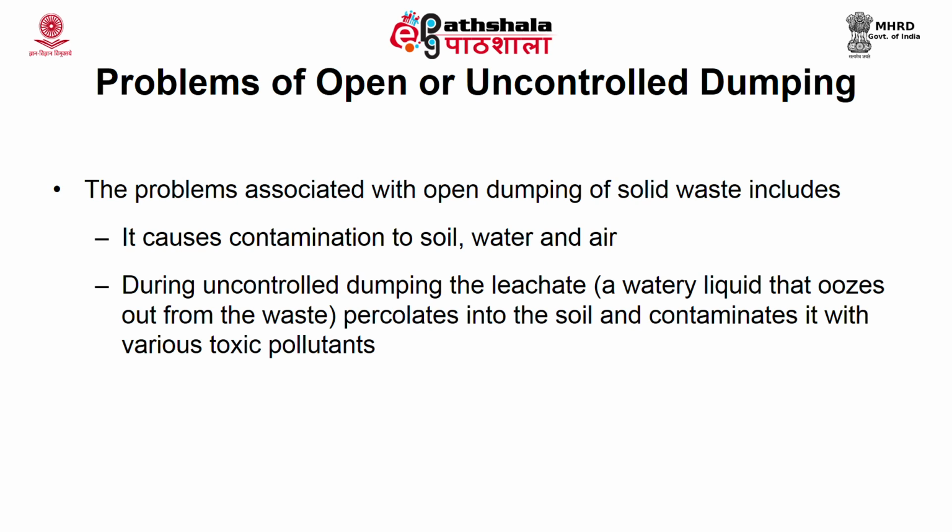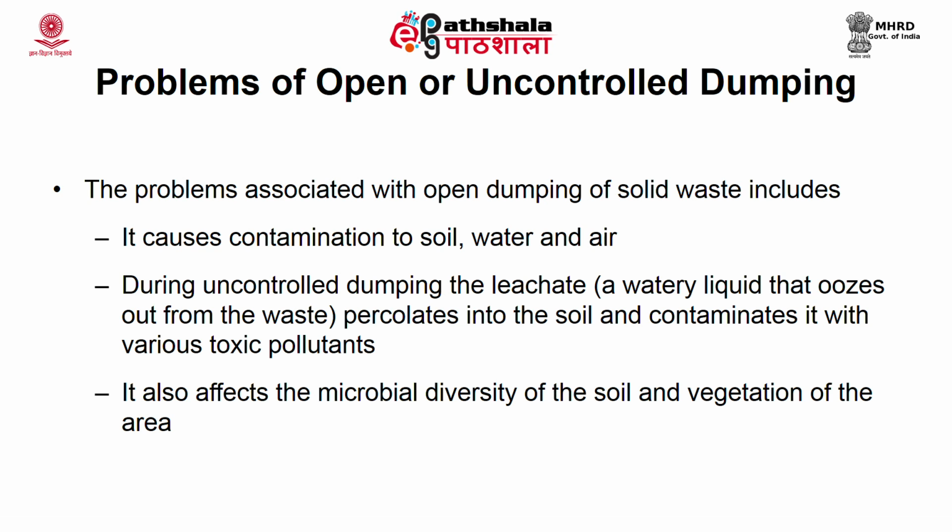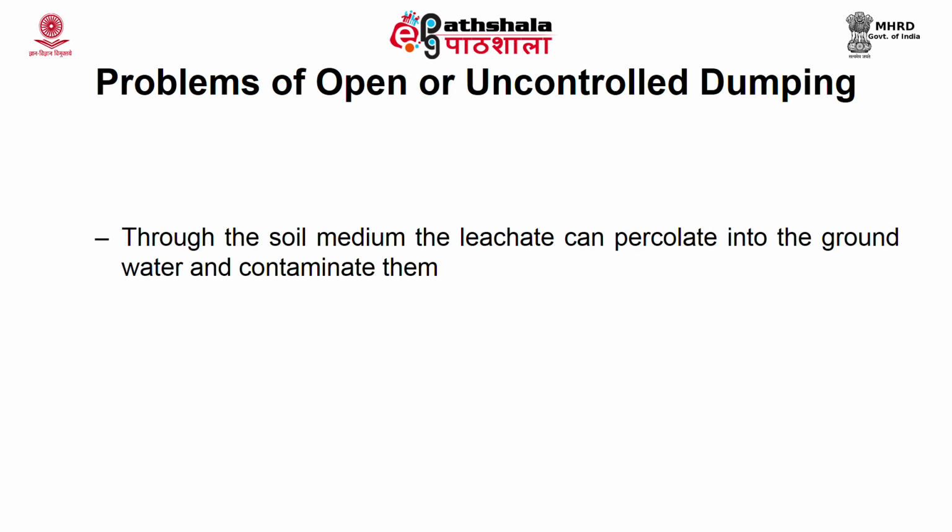Now, these contaminants may or may not be toxic. It also affects the microbial diversity of the soil and the vegetation of the area. Wherever you see these dump sites, you hardly see any vegetation; the area is sparsely vegetated. Through the soil medium, the leachate further percolates and infiltrates, and finally reaches the groundwater, thereby contaminating it.